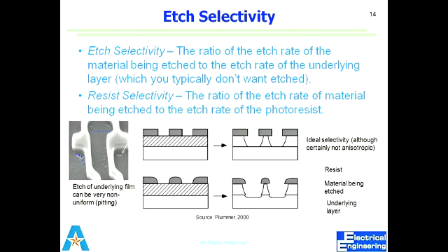Etch selectivity, the second thing: the etchant should be very selective as well. So how selective it is with respect to the mask, we termed that the film to mask etch ratio. If you remember, I told you how you practically calculate it: you calculate what is C, what is D, and C by D is actually the film to mask etch ratio. So that's how you calculate that.